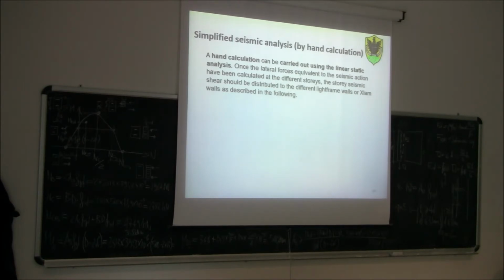Yes, you did a kind of matrix analysis, because you also had some walls, if I remember well. So you built the stiffness of the different stories of the frame and the walls, and then by doing this analysis based on the stiffness, you could understand how much of the total seismic force was applied, for example, to the frame that you decided to design.